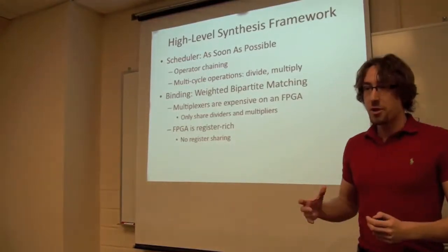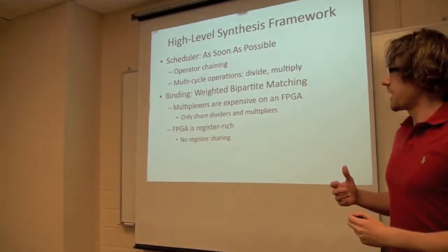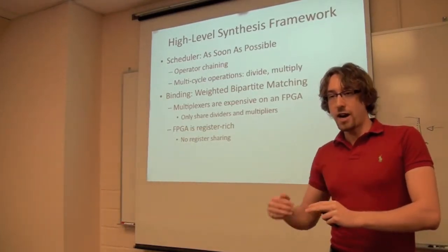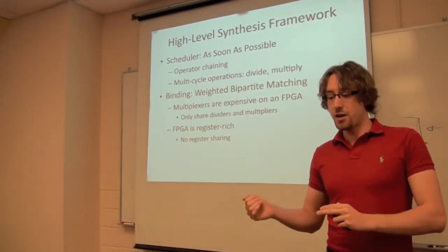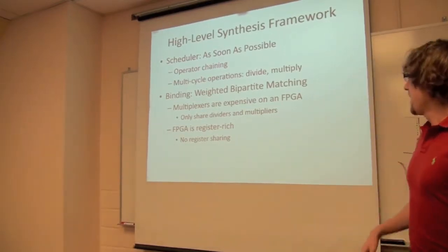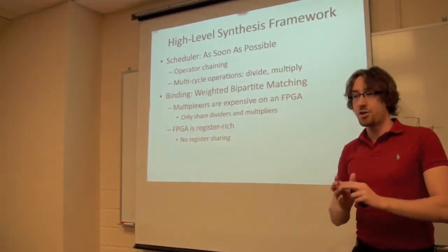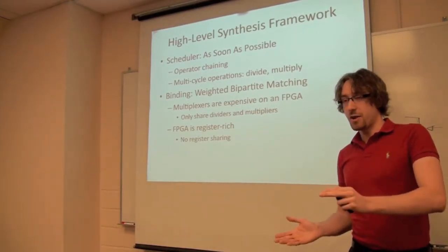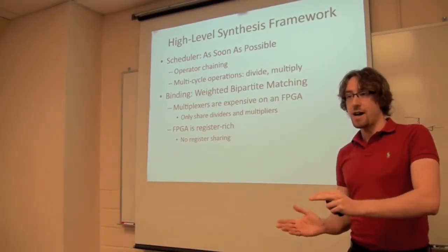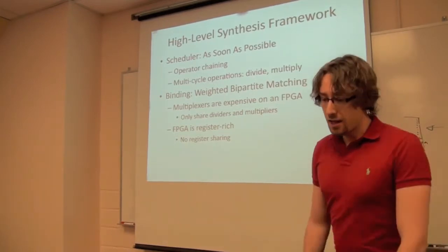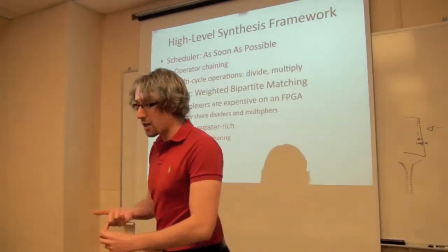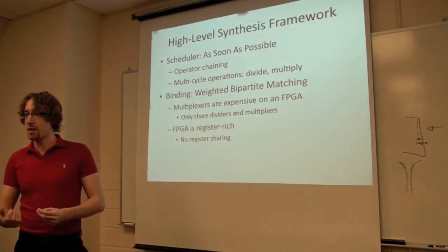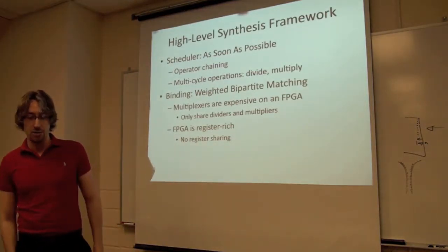So far what we've built up is a simple scheduler. It's called as soon as possible. Each operation is scheduled in the state right after all of its dependent operations are available. Our scheduler also supports operator chaining. For instance, if you have a clock period that has some space to spare, you could have a few dependent adds within the same cycle. And we also support multicycle operations, which you need for, let's say, a divider. You can't have a divider happening in one cycle. You need to pipeline that over many cycles.